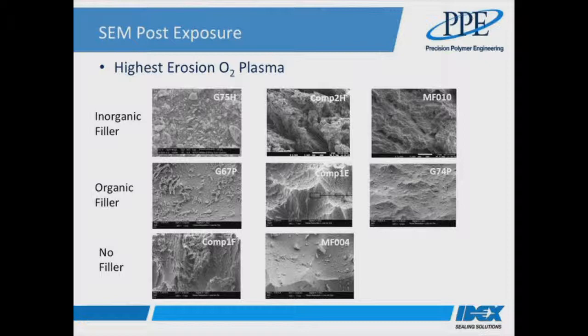The organic materials equally show different behaviours, in some cases relatively smooth surfaces with a range of what look like elongated and distinct surface features, to coarse roughness and relatively large etched features to a fairly smooth morphology. Even the filler-free materials show some big variations in surface morphology, with obvious potential to create particle contamination to a greater or lesser extent. So clearly, filler-free materials may not be completely particle-free.